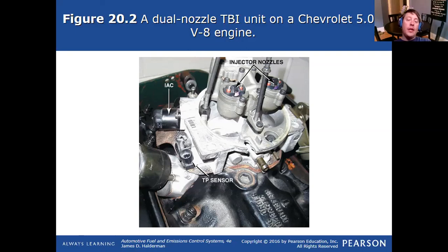So think about atomization for a second. How well is that fuel going to atomize? It's sprayed not really under vacuum. It's just spraying fuel like a bottle spraying fuel. It's spraying liquid fuel under maybe 10, 15 psi pressure, so it's not even a very strong spray pattern. There's no jet on this. This is literally just dribbling fuel onto a partially closed throttle plate, where then it has to roll around the throttle plate and be sucked into the intake manifold.